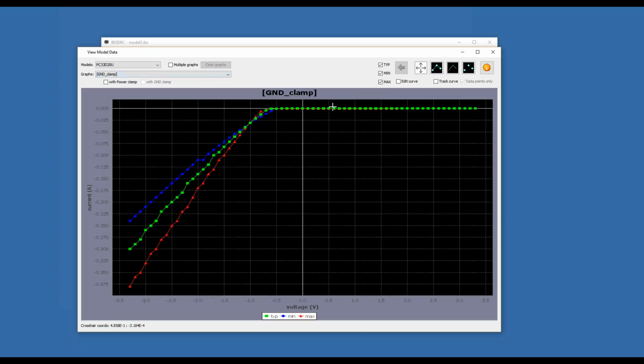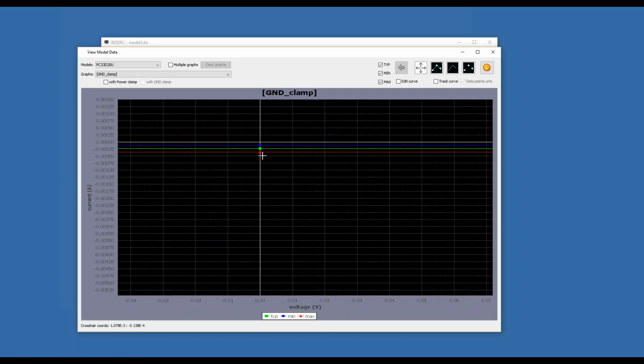What this normally means is this is probably an IBIS modeling formatter issue. Whoever created this model, either through simulation or data manipulation, subtracted a few things, and they didn't get 0. Sometimes you subtract two really small numbers and you get a small number, even though you're expecting 0. So the reality is that the I/O input in the IC probably works fine. It might be 0, but the way that the model was created is not giving you 0.